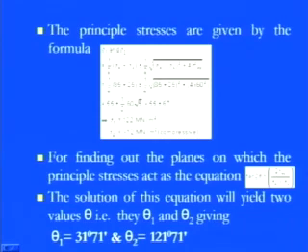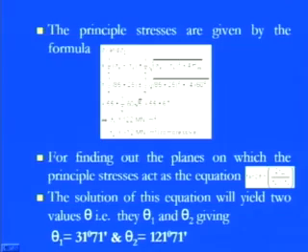Once you calculate those things, you have two values, 55 plus minus 67. So the maximum value of the principal stress is 122 meganewton per meter square. The minimum value of principal stress is minus 12 meganewton per meter square, and since it is a minus, it has a compressive nature. The first principal stress, which is positive, has a tensile nature.